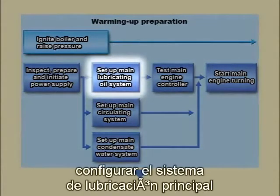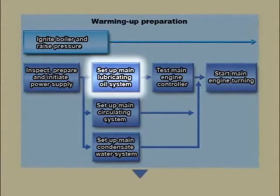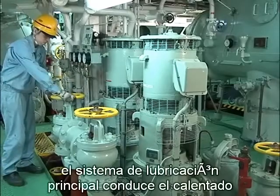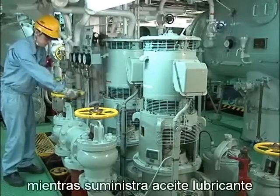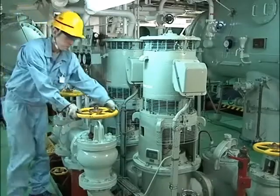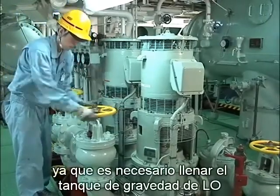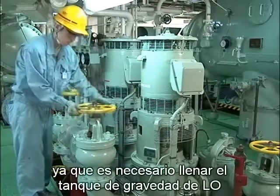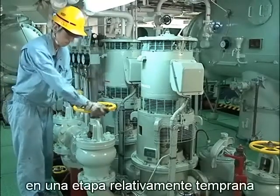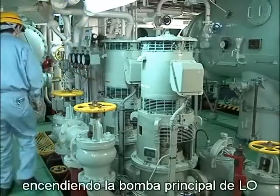Set up main lubricating oil system. The main lubricating oil system conducts warming up while supplying lubricating oil to bearings and reduction gear tooth flanks. Since it's necessary to fill the lubricating oil gravity tank, the main lubricating oil system must be set up at a relatively early stage by starting the main lubricating oil pump.